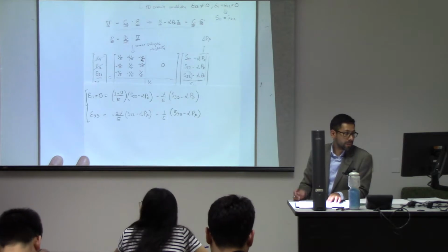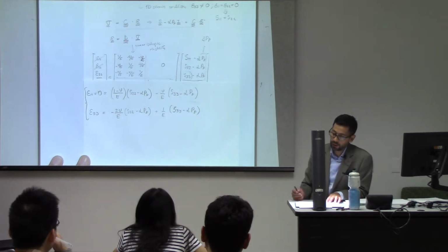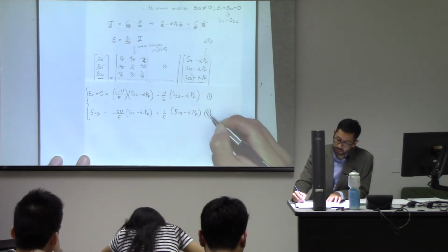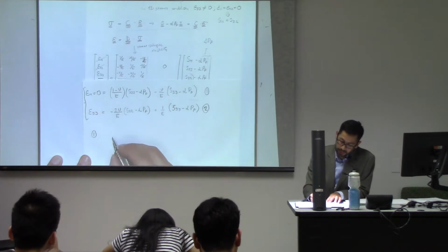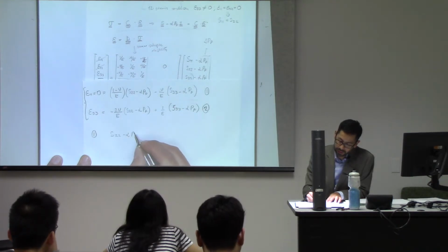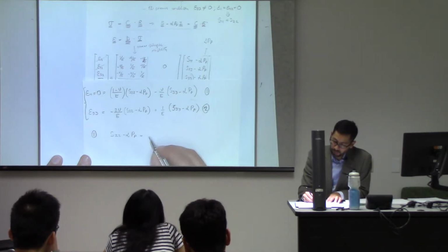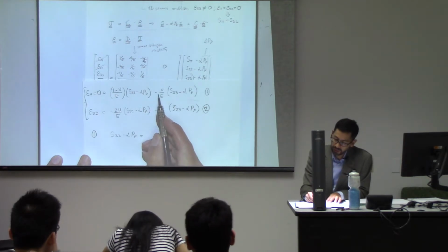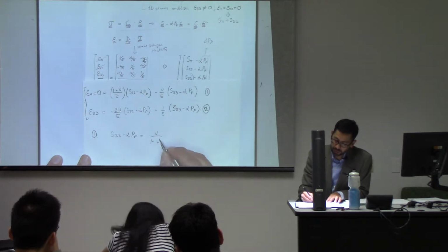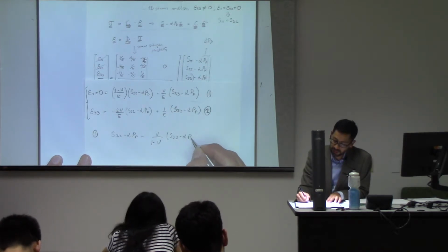And for that, if you look at the equation on the top, I have here effective horizontal stress, effective vertical stress, right? And if I wanted just to isolate, let's call this one 1 and this one 2. From equation number 1, the effective horizontal stress is going to be equal to, minus, if it goes to the other side, it's going to be positive, Poisson ratio divided by 1 minus Poisson ratio, which comes from over there, times S33 minus alpha pp.